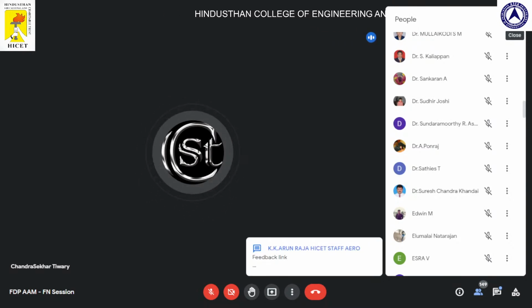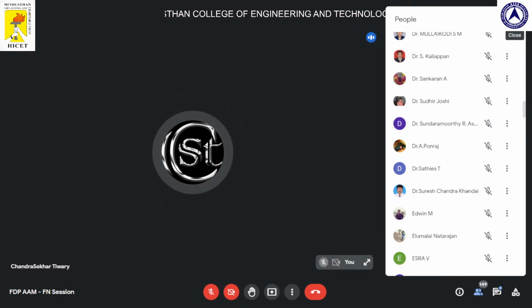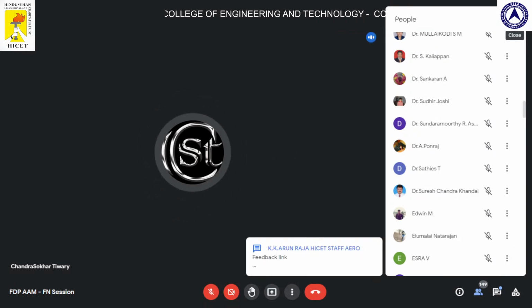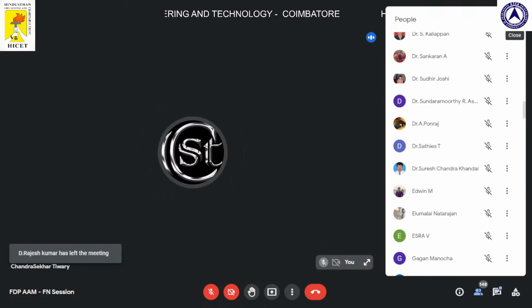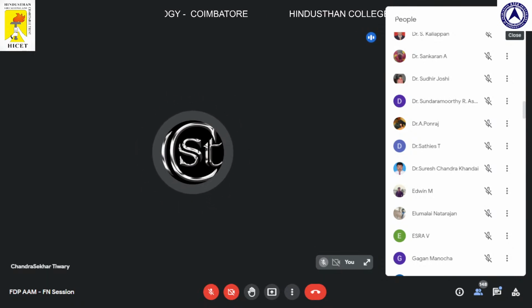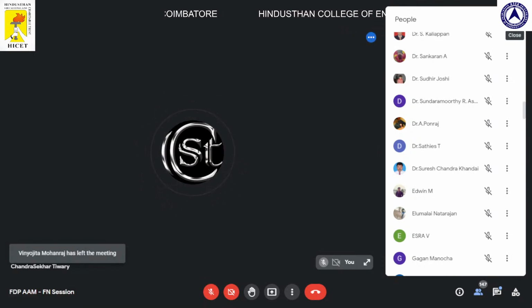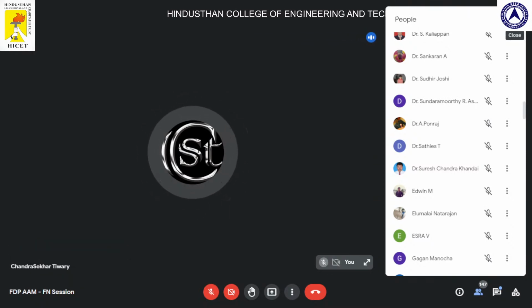Till a certain cycle. But yes, there is no focused research on porous material in the fatigue area. We have seen cyclic studies where you apply load and unload and look at several cycles, but conventional fatigue measurement on most of the structures is not done. One of the reasons, I'll tell you, is that for most 3D printed structures, especially porous ones, the standards are not well defined. So most of our studies are lab scale.